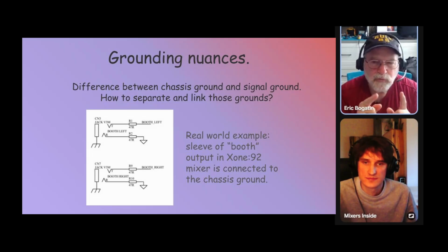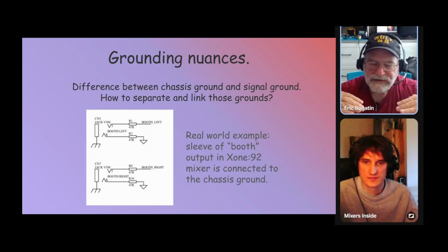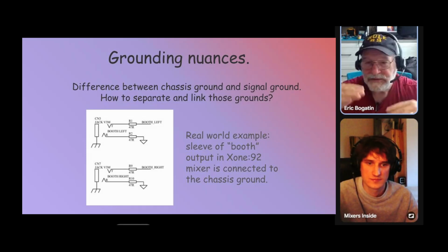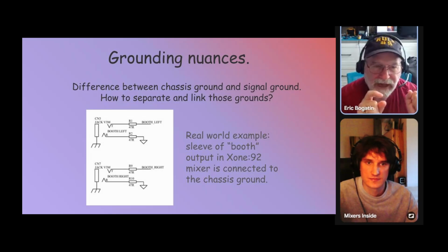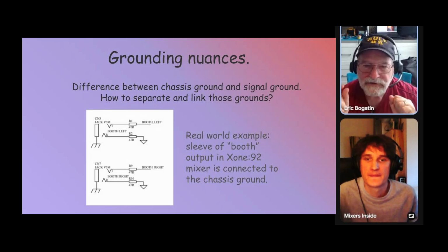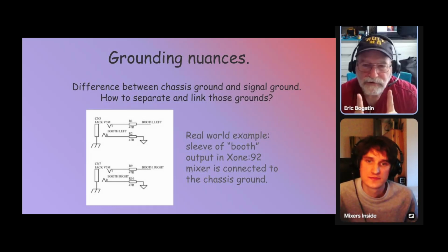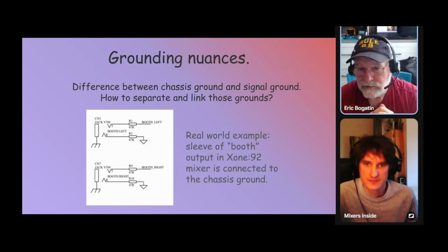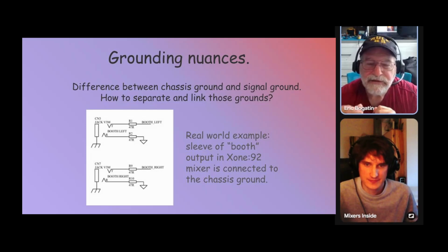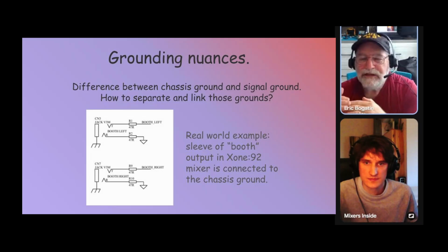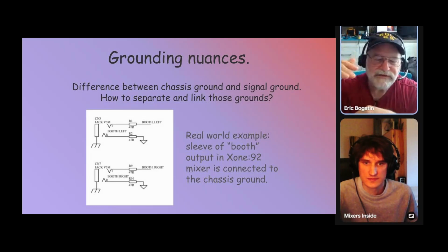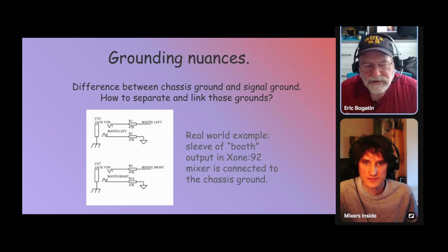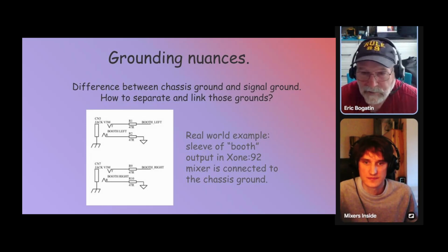If they're used as references, local references are going to have different voltages, and that's where you get noise injected with the signal. And that's where thinking about the reference path and carrying that along with the signal, and making sure you don't have any current in that reference path, is how you get clean signals without interfering noise. Yes. And that means you want to be thinking about using differential amplifiers for your low-level signals until they become high enough so that the voltage level is way above any kind of different voltage noise you're going to see in the ground plane. Yeah, sure.